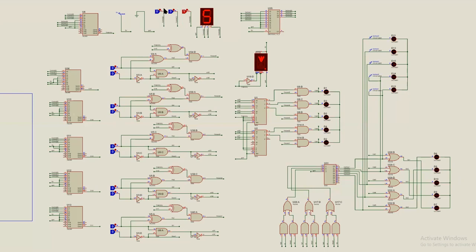What if the elevator is in between 2 calls? Suppose the elevator is on 3 and there is someone on the 4th floor who wants to go downwards, and there's someone on the 1st floor who wants to go upwards. The furthest point from this elevator position is 1, not 4. So it will ignore the 4th position and go to 1. So the 4th position is ignored. If, however, there is some intermediate passenger on 2 who wants to go downwards, aligning with the direction, it will stop there. But if the direction is reversed or the opposite, it will not stop there.